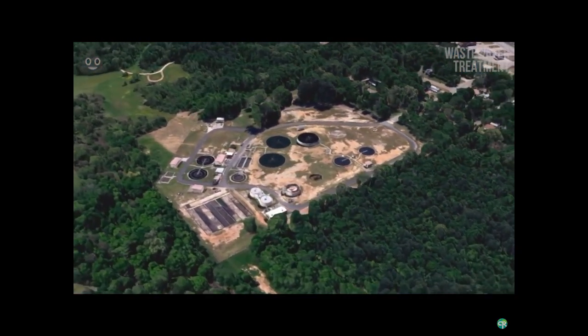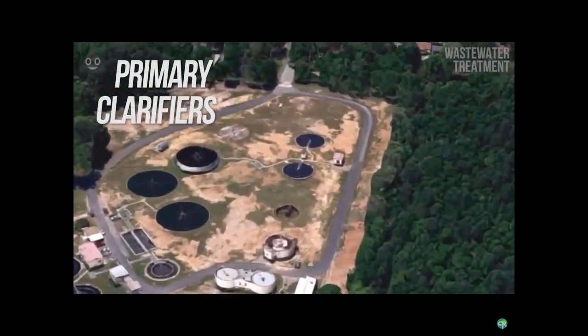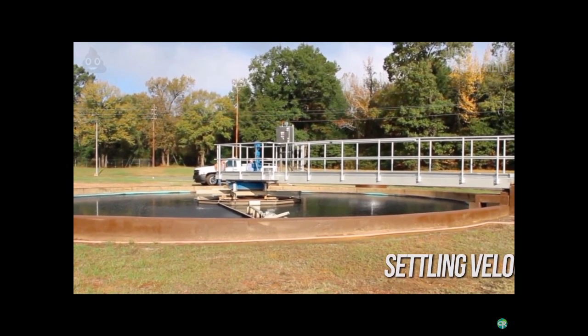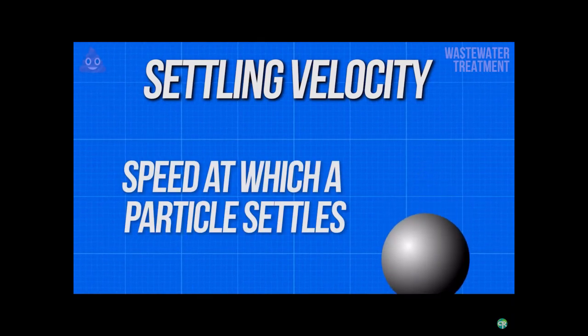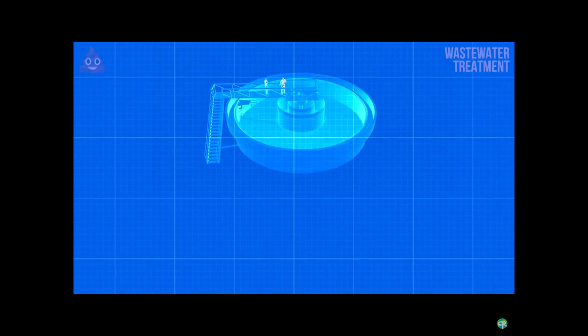Primary clarifiers, and clarifiers in general, function on the principle of settling velocity. This term can be defined simply as the speed at which a particle settles. For wastewater being pumped into clarifiers, it's important that the flow rate of the water being pumped in doesn't exceed the settling velocity of the particles trying to be removed.